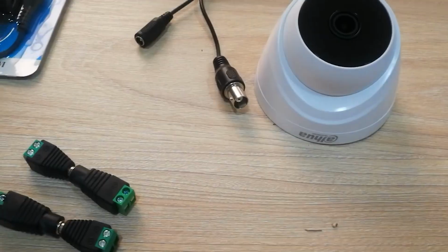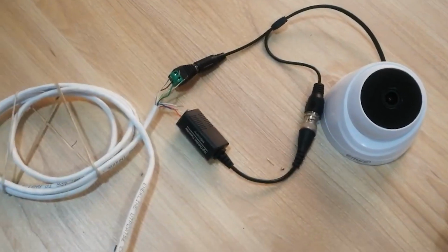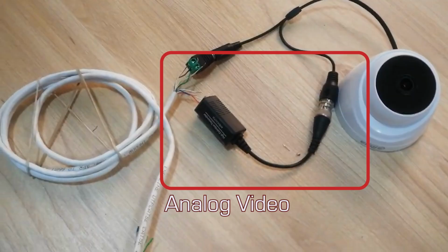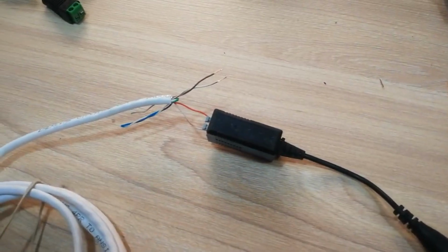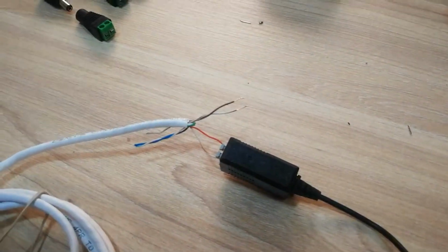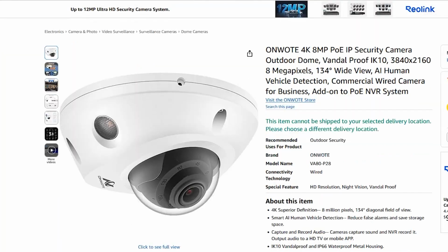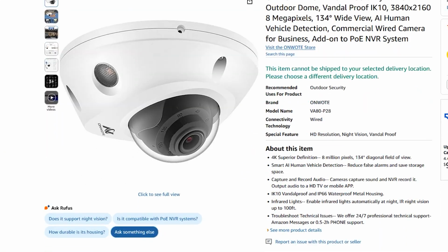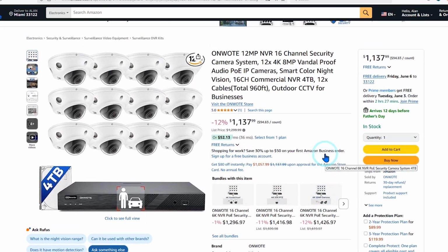The main change right here is that these systems have moved away from analog cable video and audio transmission, as we did in the past with these small devices known as video baluns, which used copper UTP cables to transmit power and signals. This allowed us to use one cable for 2 cameras or even up to 3 if we consolidated the power through one of its pairs. These new camera systems have been on the market for many years, but have finally reached commercial price levels.